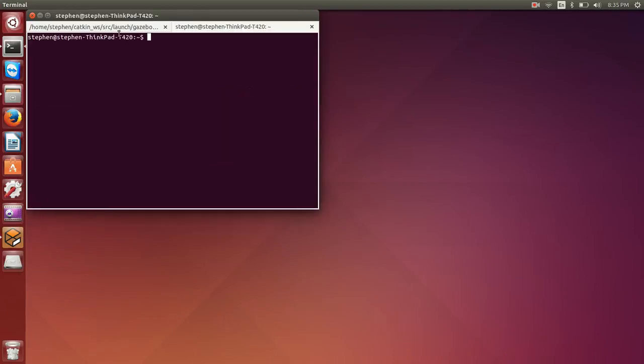Open up a new terminal, and now we're going to start Moveit. So I'm going to say roslaunch, and then the name of my file, what I call it, Moveit ABB mobile V5, and then we're going to run the demo.